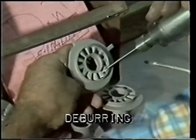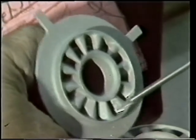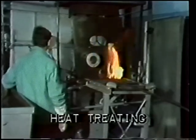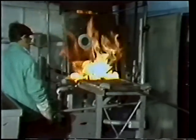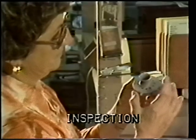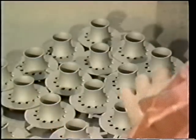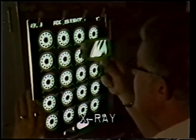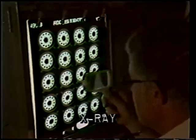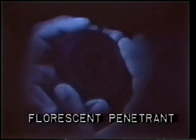Sharp edges are removed with deburring operations. In some cases, the finished parts are heat treated in order to acquire better metallurgical properties. The final casting is then inspected using a variety of different methods: visual inspection, X-ray, and fluorescent penetrant inspection, which uses an iridescent dye that seeps into defects, which are then illuminated with an ultraviolet light.